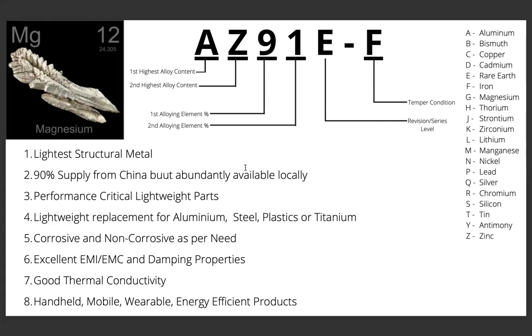magnesium. If you are looking at building machinery and equipment which is handheld or has to be mobile or wearable or is energy efficient, which in our experience all modern machinery and equipment is falling into this, you should seriously consider magnesium as a potential non-ferrous alloy.